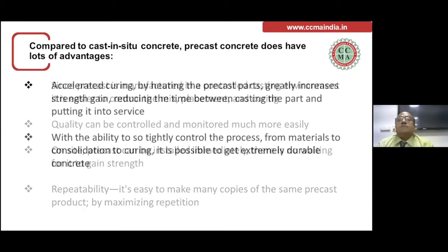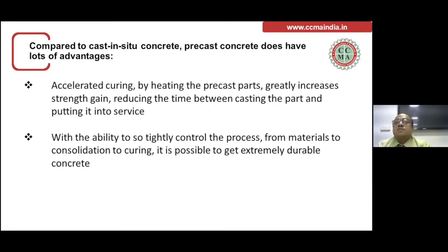Now, what are the advantages of precast concrete versus cast in situ concrete? One is accelerated curing, possible by different methods, maybe heating the precast parts, or various methods that will come later. Because the process is tightly controlled from material to consolidation to curing, extremely durable concrete is possible. That is the benefit of the precast industry compared to any cast in situ concrete.